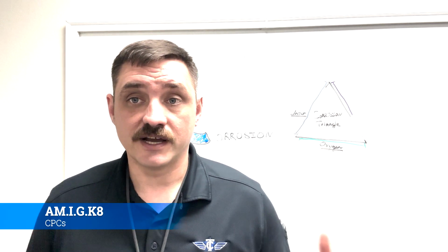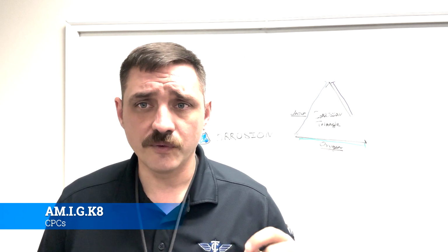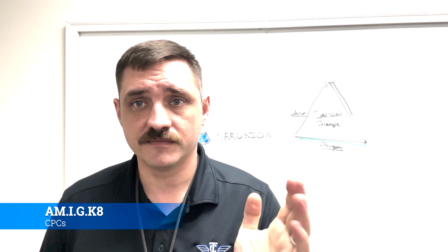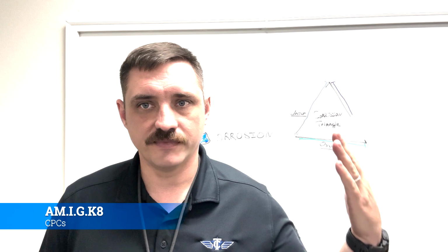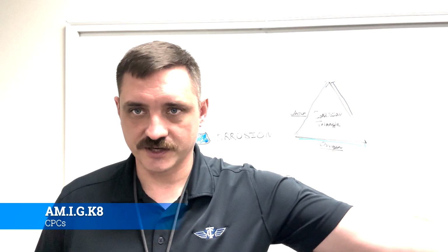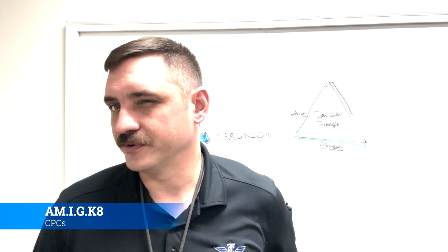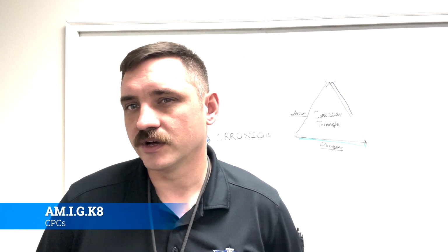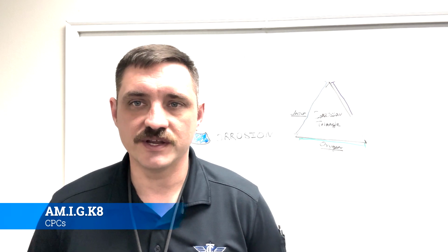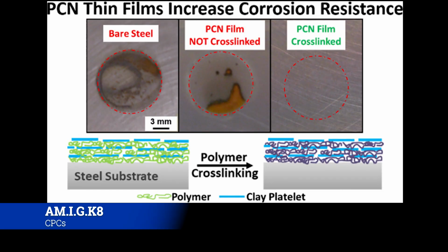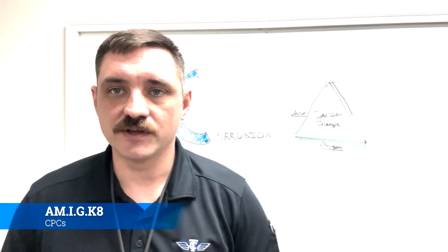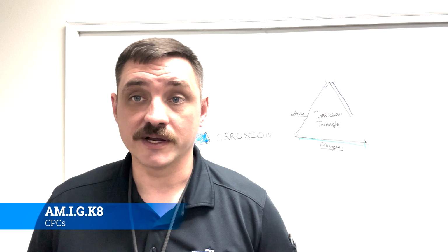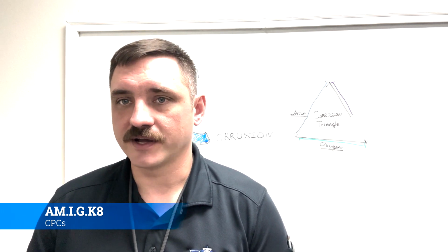So that's LPS3. There are also what are called thin film dielectrics. A lot of times they are dielectrics that are put on parts that eventually go on aircraft. Not something that you have to service on a regular basis. You just know that you need to preserve that film that's on there. But that is a type of CPC, a corrosion preventative compound, an inhibitor that takes the metal out of the equation, just like our zinc chromate does. Very, very simple application to that, and not something you have to service.